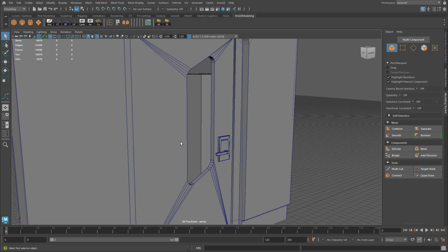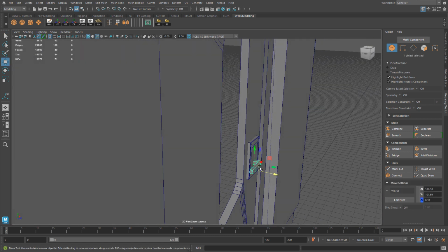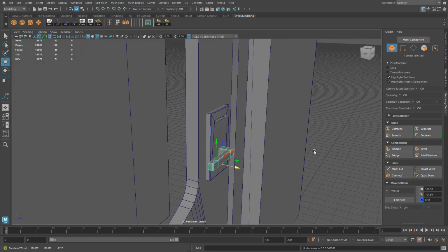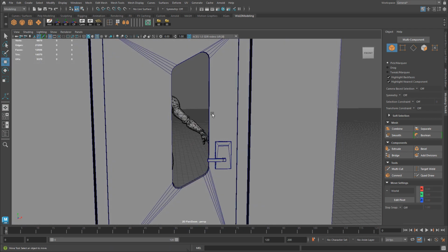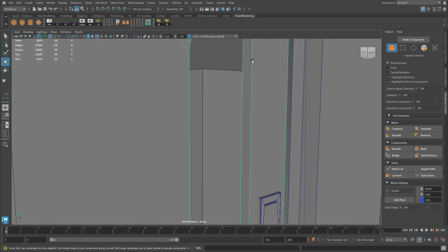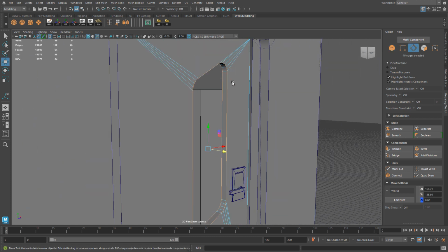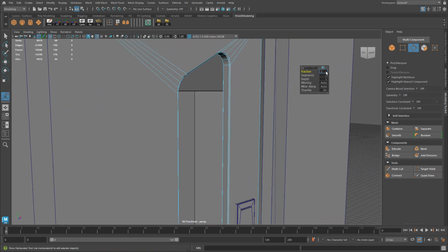Will the player see this? And even in first person view, we didn't really see that much. But I just want to show you how to do that to an entire object. Create a little bit of a detail on the handle. I do want to add the glass with a single plane, and then I want to curve and angle these corners right here on the inside. So let's actually do that first. I'm going to select all those edges. Let's do Control B to bevel them, and let's do 0.75.